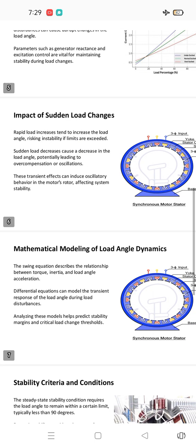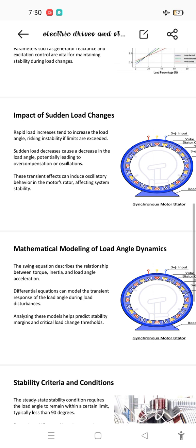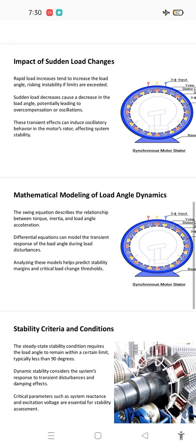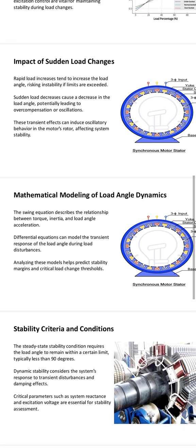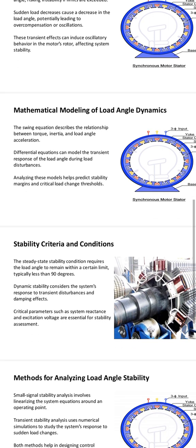Mathematical modeling of load angle dynamics. The swing equation describes the relationship between torque, inertia, and load angle acceleration. Differential equations can model the transient response of the load angle during load disturbance. Analyzing these models helps predict stability margins and critical load change thresholds.